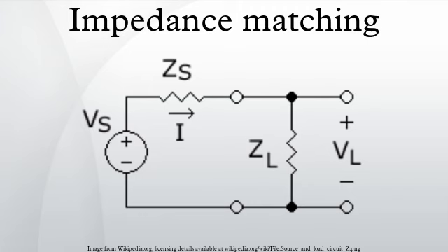Power factor correction. Power factor correction devices are intended to cancel the reactive and nonlinear characteristics of a load at the end of a power line. This causes the load seen by the power line to be purely resistive. For a given true power required by a load, this minimizes the true current supplied through the power lines, and minimizes power wasted in the resistance of those power lines.